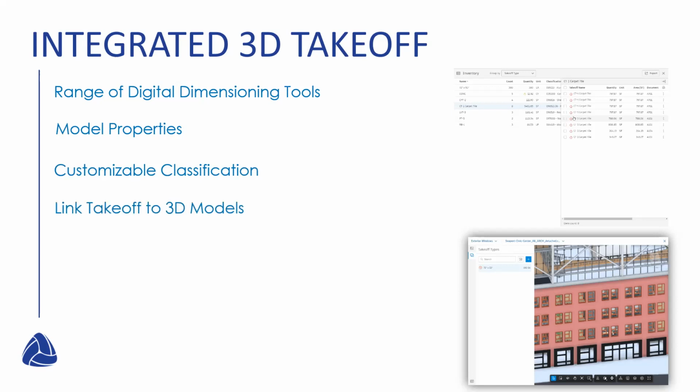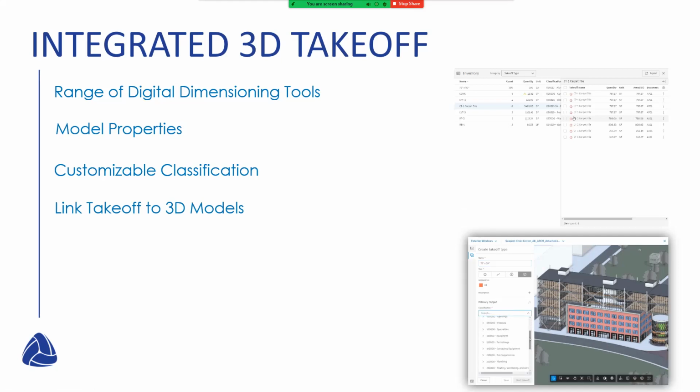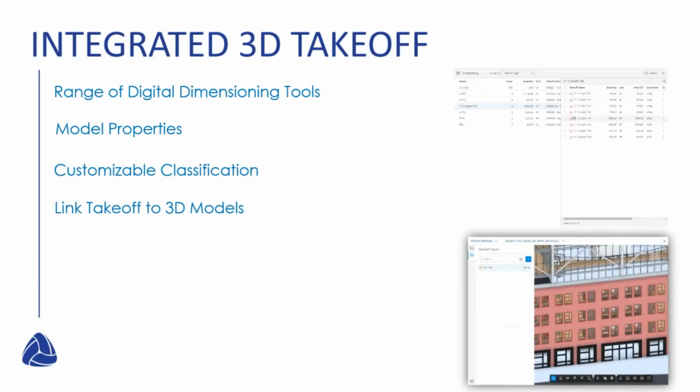Another item is we can link takeoffs to a 3D model. So again, if I play that video for you below, you will notice that my takeoff series is coming from the model. I'm not starting the takeoff and then linking to the model. The moment you open up the model, you can start your takeoff and quantifying process. So we are quickly generating quantities from building information models to save time in visualizing project scope.